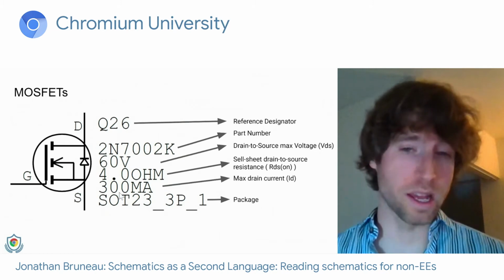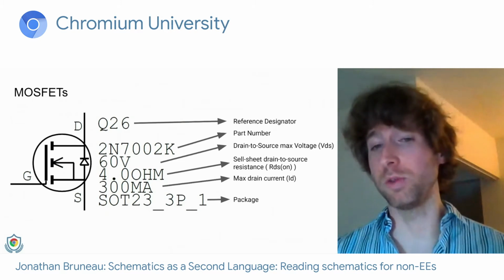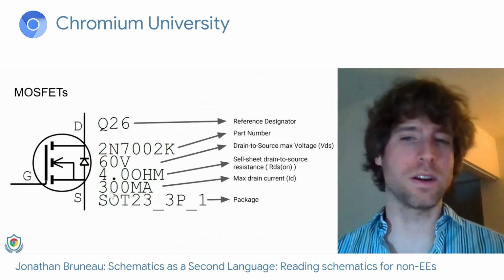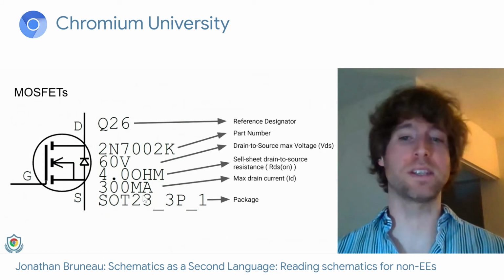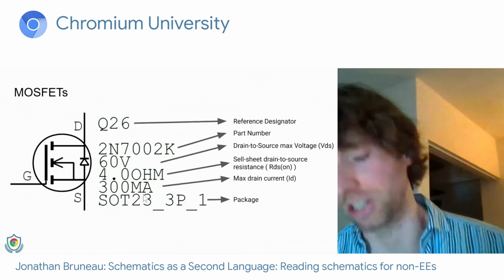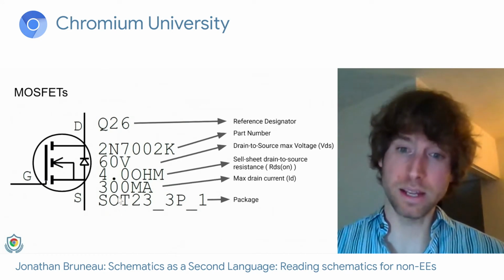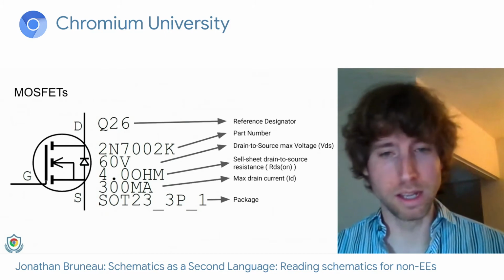It's worth noting here that our amazing CAD tools don't really do case, so everything is in capital. So you have to use a little bit of judgment here and realize that 300 megaamps is a huge amount of energy, and this isn't actually 300 milliamps. Sorry, if you could fix that problem, I'd love it.